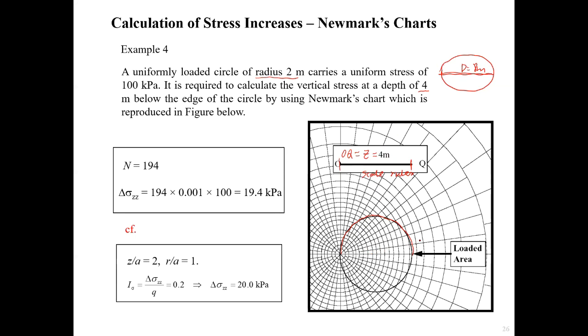Is that clear? Because the J and OQ are 4 meter, and your D is 8 meter, it should be this length, so roughly here. Now your circular loading area will be this one. That corresponds to the circular loading with a radius of 4 meter or diameter of 8 meter. You can double check that this diameter is double the length of this OQ.